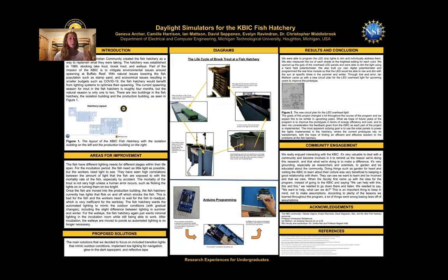Adding an RTC, or a real-time module, allows the Arduino to connect to time in the real world. And so what that'll allow us to do is connect the time within the circuit of the LED panels to the time in the real world, so that when we want it to rise at a certain time and set at a certain time, it will be able to do so. And even with subtle differences between summer and winter, we'll be able to take into account the differences in the amount of light during those seasons.